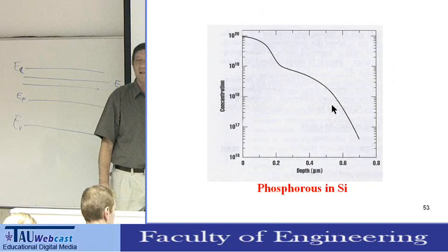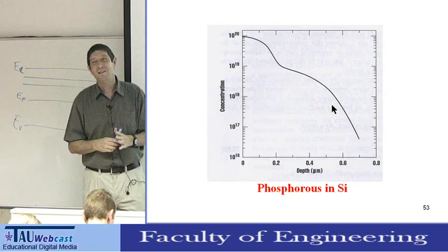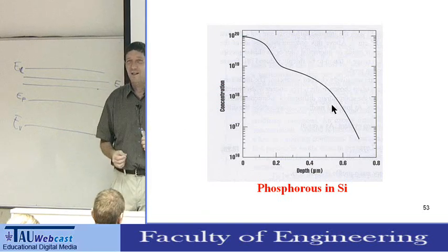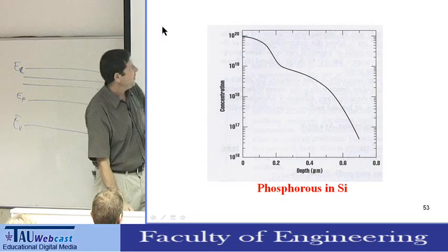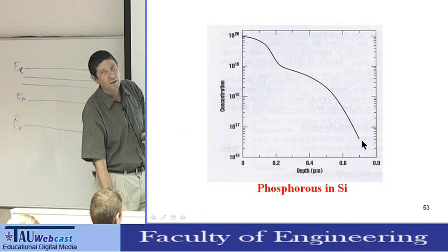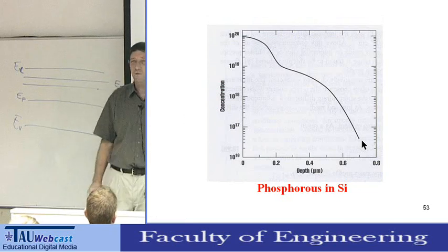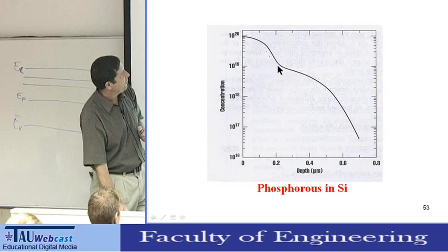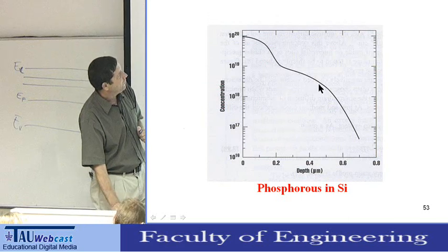Before we end this lecture, I want to show that things can be even more complicated. Let me first finish phosphorus. In phosphorus diffusion, we see one diffusion and a second diffusion. This was discovered actually when people processed bipolar devices. You can see here that you expect the profile to go like this, so you expect the junction to be here. But the actual profile goes like this.